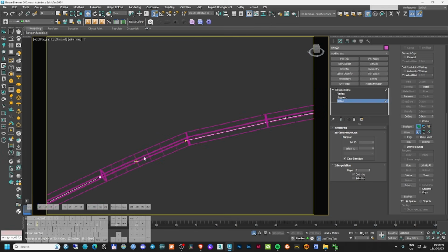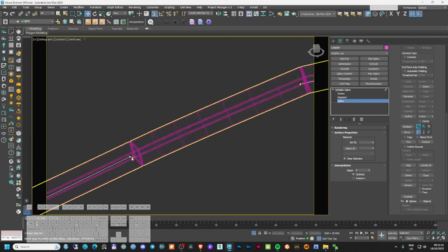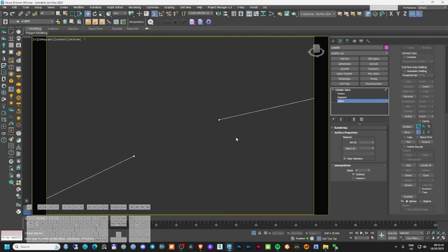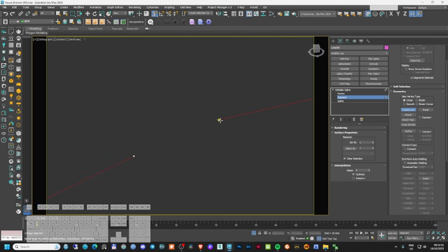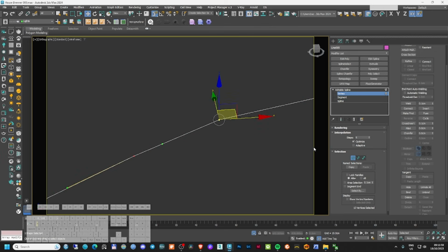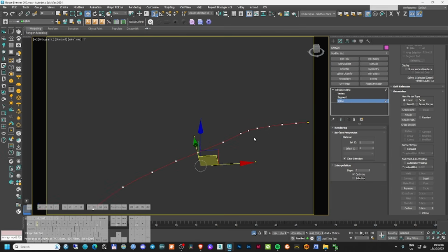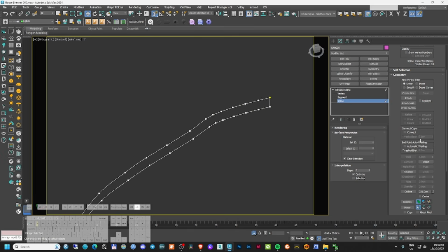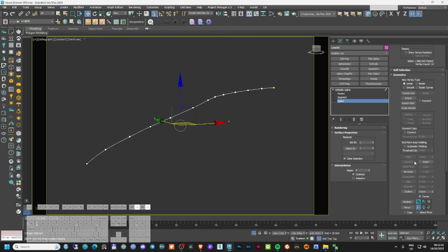The problem is that we are missing here one segment, so we need to create this, create line, weld. Now go back to vertex, select all of them, weld together. They can be also one, and then now if I use the outline it should go. So yeah, unfortunately this is not really working.